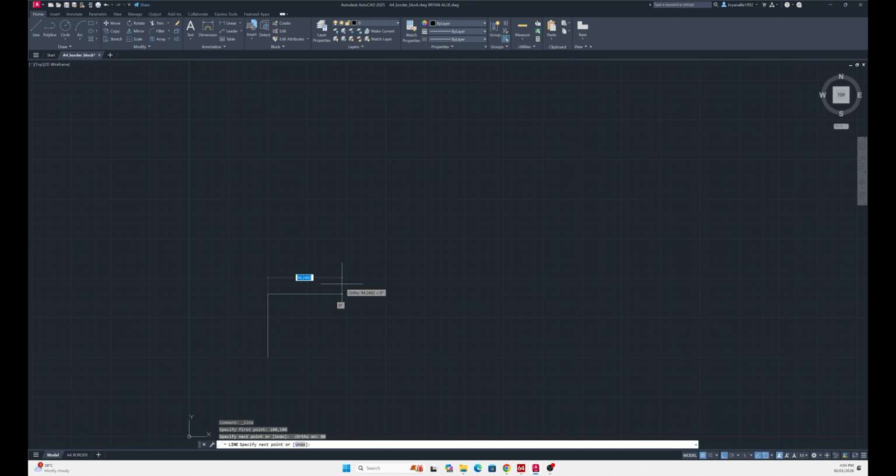And once you've done that, because it's asking for each point, instead of just adding dimension, I'm going to press escape, press spacebar, or press the line command again, whichever one you prefer. So again, we're going to do the same thing. So point 2 is x is 100, so it stays on the x-axis. Then the y-axis is 180.